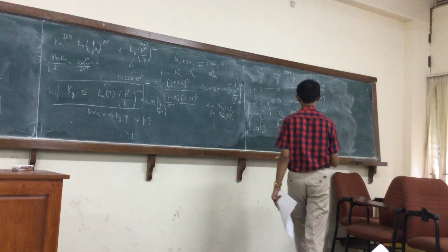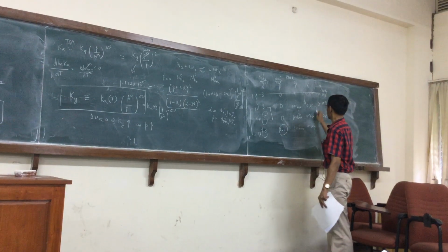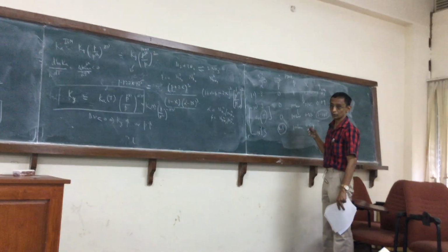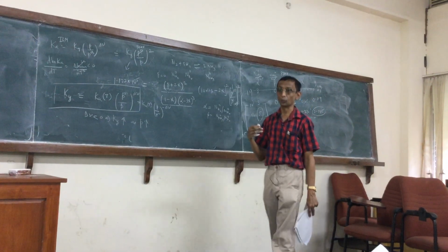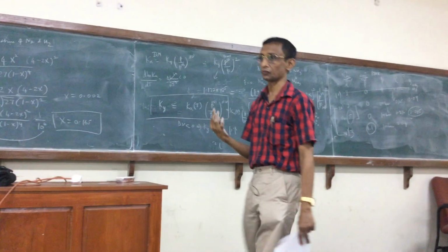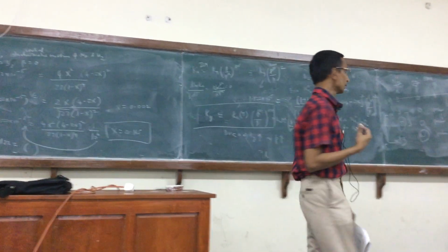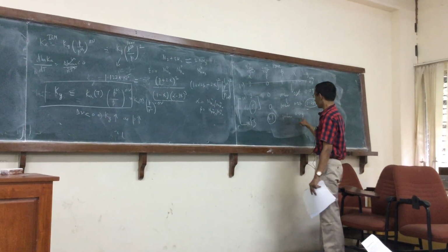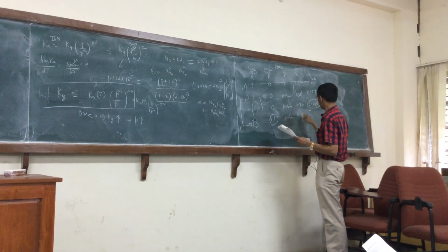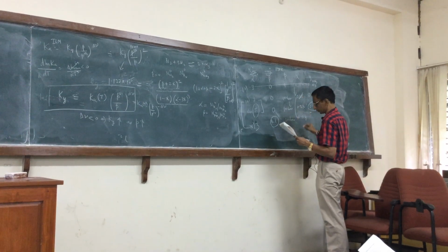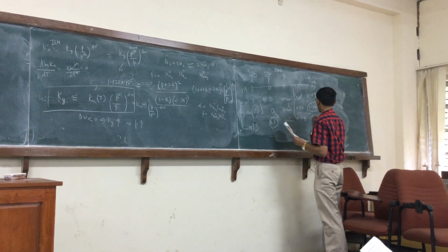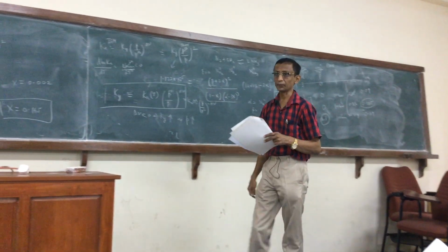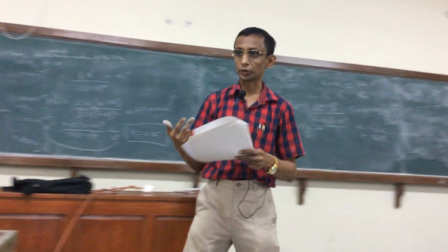So you have to again worry about whether you want higher conversion or a higher final value, because if you want to separate out the ammonia, we obviously want a higher mole fraction of ammonia to be present. From that standpoint, this is probably a better condition. Again here, we see the conversion has decreased, but the mole fraction of ammonia remains the same. That's because we are using some extra ammonia to begin with.